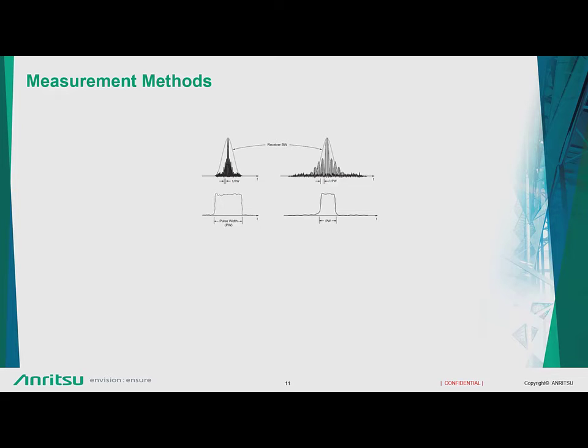So in the traditional methods for the measurement system, normally the instruments are limited by a receiver, or I should say IF, bandwidth of 5 to 10 megahertz, right? So if there is a pulse which has a broader or wider spectrum, that means if there is a narrower pulse, then the entire spectrum content cannot be processed by the measurement system. I'll come to that, but let's see what happens in the traditional method.